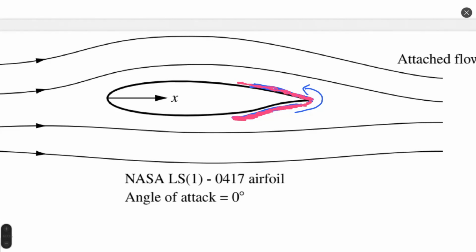So pressure on upper and lower side of airfoil will be equal because it happens inside almost zero velocity inside the boundary layer. And because this pressure is high, flow separation appears. Flow goes in this direction. Since flow goes in two different directions, at some point they should interact. And flow separation starts. The higher the pressure difference or pressure gradient, the higher these forces to provoke flow separation.